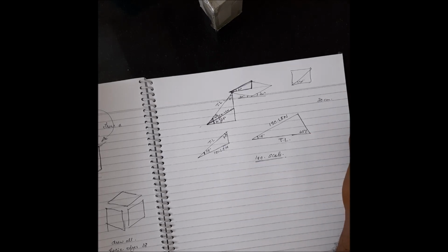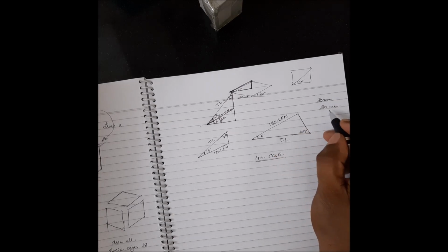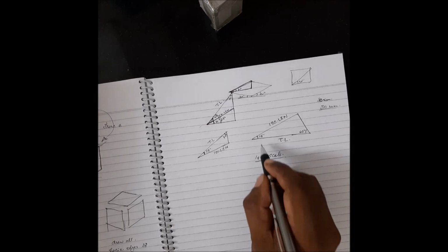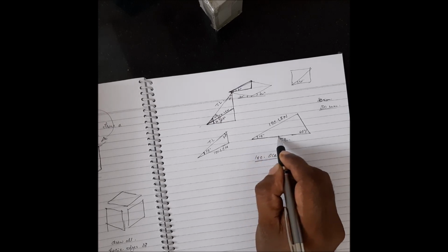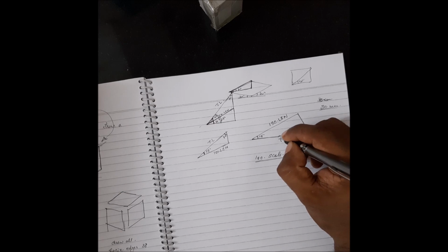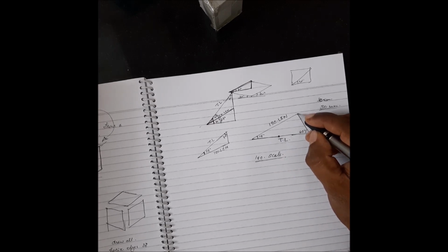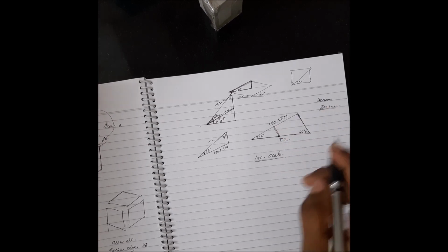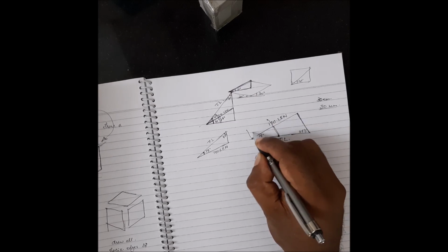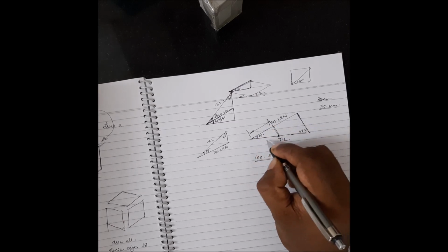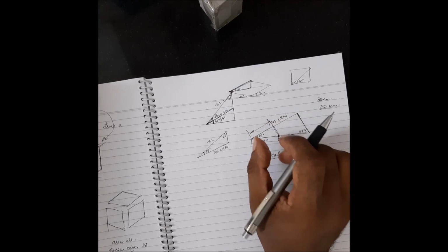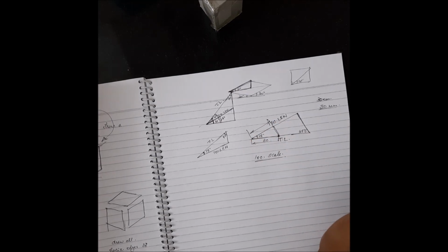millimeters, sorry, 30 mm. To find out the isometric length, all you have to do is take this 30 mm in your scale, measure from here to here as 30 mm distance, and then from this point, draw a line which is exactly parallel to this line, like this. So this length is your required, if this is 30 mm, this is your corresponding isometric length.